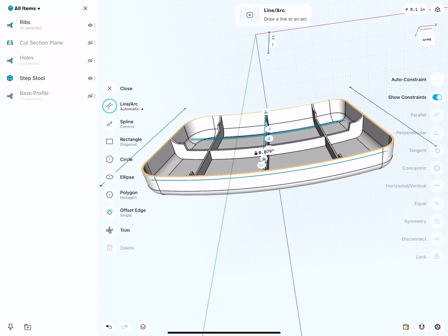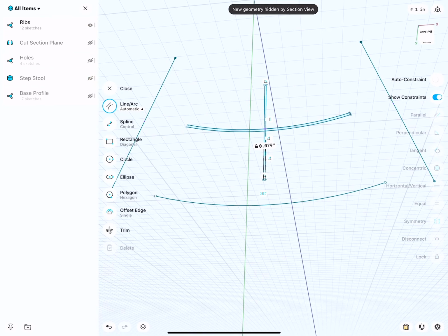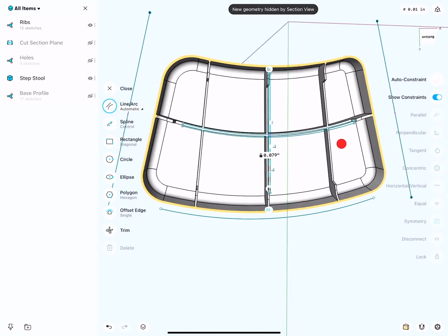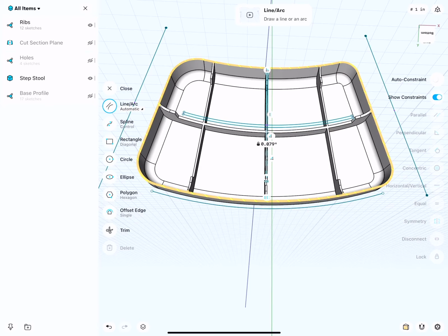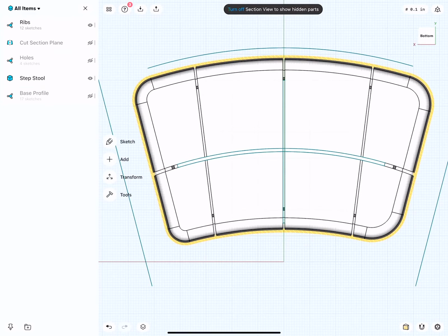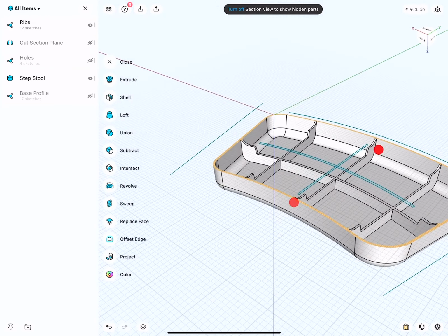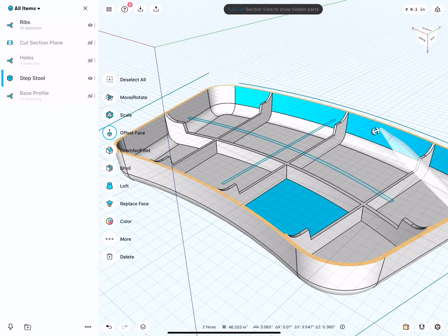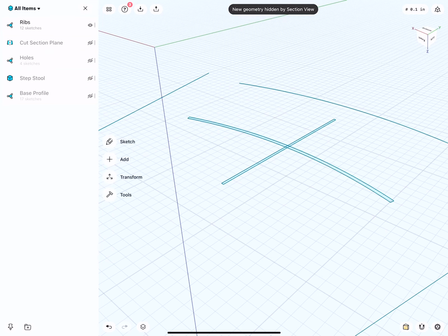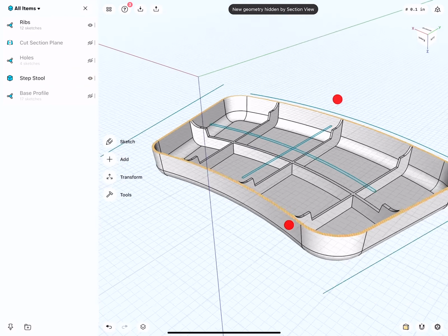The ribs, if I quickly show the sketch, as you can see, are very basic. I did not sketch this out in much detail because all the elements we see here are pretty much the same, and I simply built basic geometry elements and then used the replace face command to join the extrusion onto the bottom and the side faces. And that worked out really great. So not much work with a sketch, very basic. And then the rest I simply did via smart modeling commands.